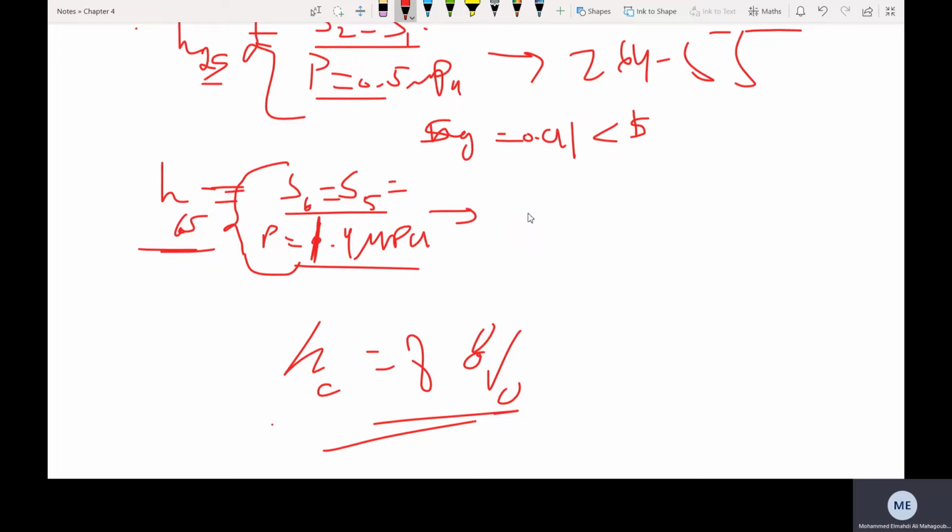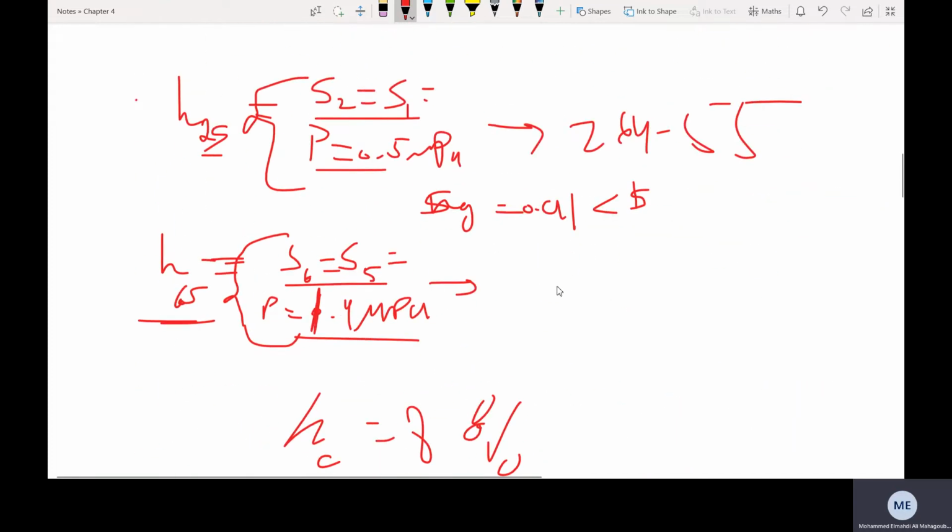And now I'm going again to the superheated tables, but now for a different pressure, which is 1.2. Now I'm searching for 0.92. I can't find the 0.92 exactly, which is actually at 278.27, so it's going to be around that value, but it will be different in the decimals.